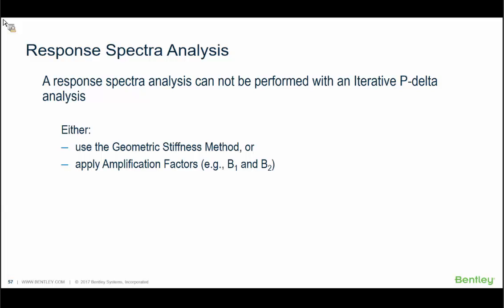To include the effects of P-delta, either use the geometric stiffness method along with the response spectra analysis, which is what RAM Frame does in the RAM Structural System for the large P-delta, or calculate the amplification factors and apply them to the response spectra analysis results.